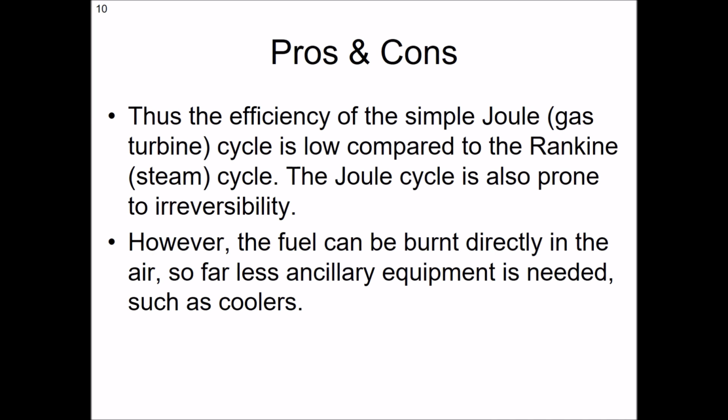All right, so the efficiency of a simple gas turbine is quite low compared to, say, something like a steam cycle. And there's also a lot of irreversibilities in here, so we do actually get a lot of noise. Well, I mean, the video is pretty much a testament to that, isn't it? So you're throwing a lot of energy out the back of the system at very high speeds. Now there's a great irony in this: if we're looking at jet propulsion, that's exactly what we want to do.